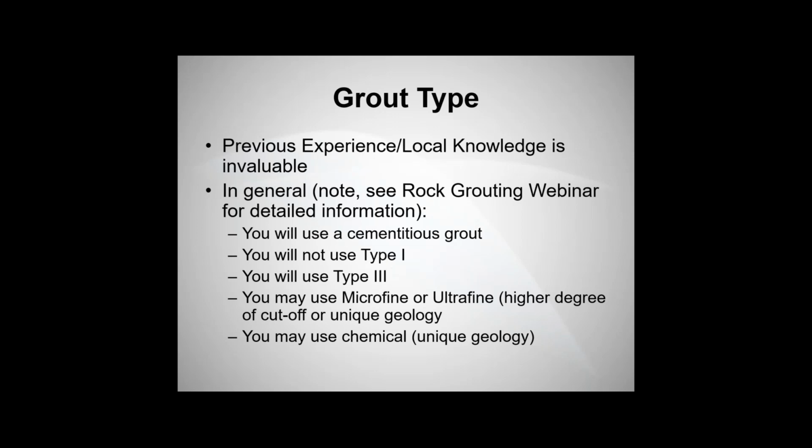We get into the grout, which is the next probably important thing to consider here. Grout type, again, we had an entire webinar on this, so refer back to it if you need more information. But the number one indicator, in my experience, of what's going to be successful when it comes to grout type is the previous experience on that site, or some local knowledge of the geology. So it comes down to the geology.